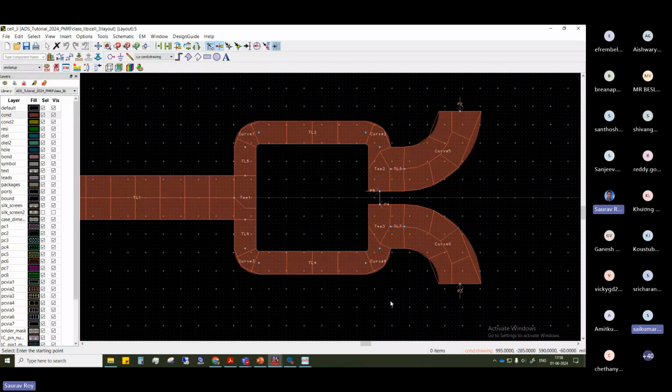When you are simulating that result, in EM simulation, is there any change compared to what you have done right now? You have converted to the symbol and you are placing the resistor. Now in EM simulation, you are not placing the resistor. No, in EM simulation you cannot place resistance. You can just do the 3D components only, microstrip lines and so on.